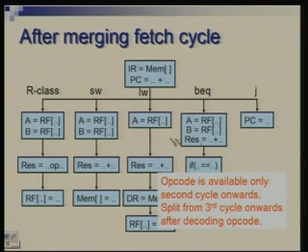So what if we repeat this also in all the instructions? Once again the ALU is free, we are not doing anything with it. So if we occupy the ALU in an activity which we may discard later on, still there is no harm apart from energy consumption. Also the result register is not holding any value which will get overwritten here. So let us try to make this a common action for all the instructions.